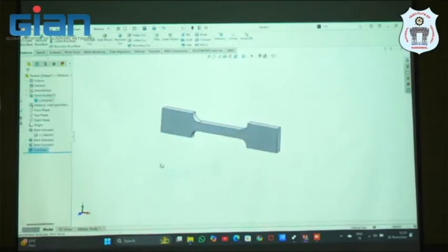Suppose if you are getting this body, you can still do it in Altair also. That example we can see for the bones. Why can't we do it in SolidWorks? Because bone is an STL file geometry, because that is a 3D scanned geometry, right? So we cannot design the bone patient to patient. We can scan the 3D model and get it in the STL file tessellation format. So bone is in STL file format. So we can play in the bone; options are available: how to cut the geometry, how to define the design space, non-design space.